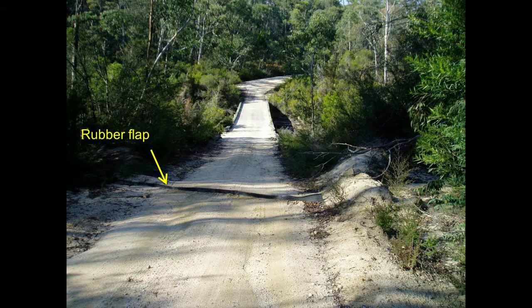So basically, it's a temporary structure that water flows down the road, hits the flap, and is diverted off into undisturbed filter strip. The advantage of these for trucks is that basically they will obviously lie down when the truck drives over it and then stand up again. So they're obviously not a permanent solution because they do wear out over time, but certainly when the road is needed to be used by a heavy vehicle, frequently they're a good option.